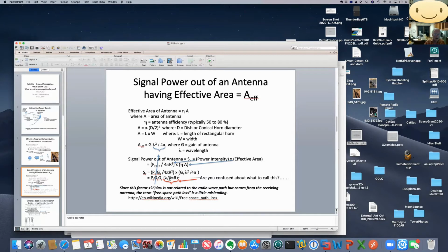Calculate the intensity hitting the antenna, which is proportional only to one over the range squared, and the effective area of the antenna, which is this equation here. And just multiply those two. So that's what I remember. And once I remember those two things, I can solve just about any problem involving how much power you are getting out of the antenna.